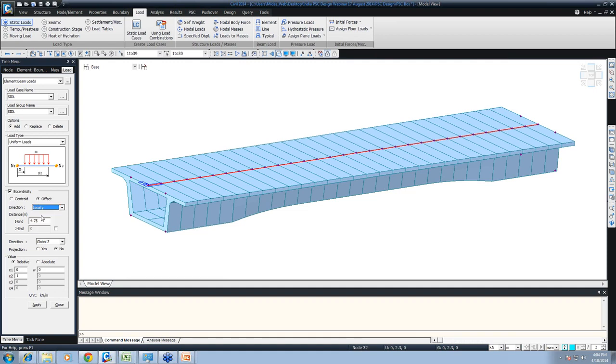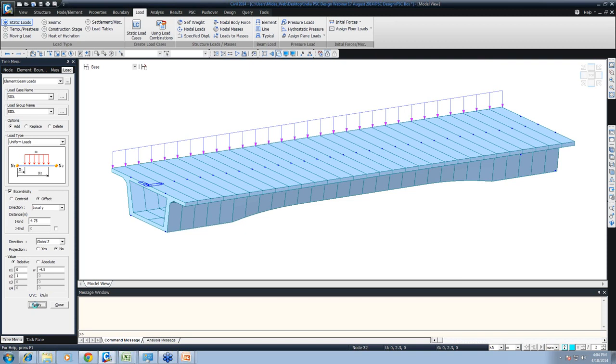Since it is not a curved base, the local Y axis will be aligned along the global Y axis. So there is no need of giving a global Y or local Y. I mean, you can give anything. Similarly, global Z weight, the loading direction, I can give here. So this will act in one end. Similarly, we can again choose all the section properties and give it on the other end. So this way we are activating SIDL for the railings on both the ends.